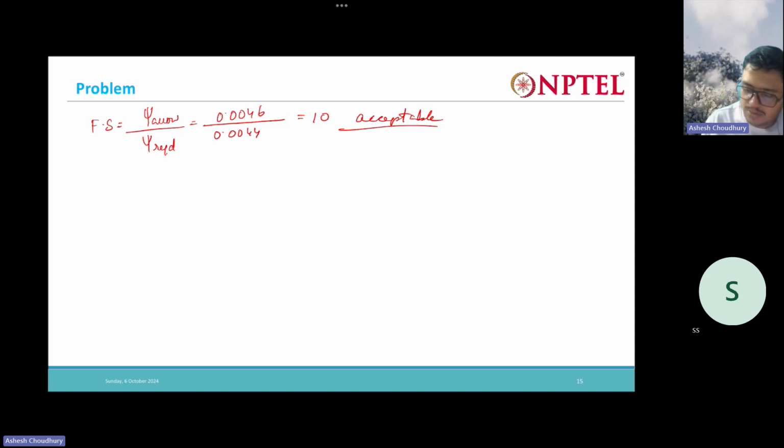So you understood, right? You have water levels like this, and you have the geotextile placed like this. When water is coming down from here to this level, there is a tendency for the water to take out the soil particles with it. That's why you put this geotextile here.